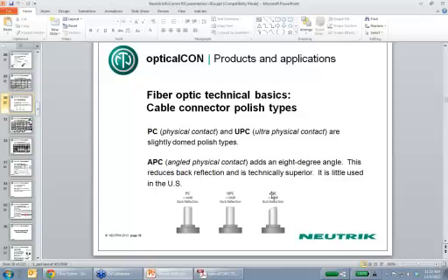For those of you listening, if you take your index finger from your left hand and right hand and put them right together, pointing right at each other, you would think that would be the best way to transmit light, just right through. But it turns out if you actually angle your fingers a little bit, or angle this fiber by about 8 degrees on each side, you get less back reflection. So imagine you're shining a flashlight into a flashlight; the lens on the flashlight is going to reflect back a little bit.